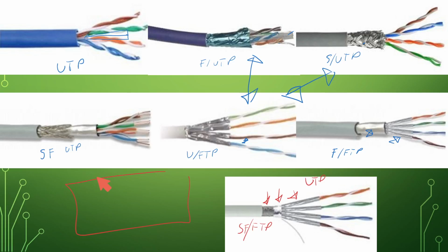Now, things have also gotten better with VFDs, variable frequency drives. It used to be that to turn a motor on, a contactor closed and it was full power to the motor, like flooring your car and spinning those wheels. That caused a huge EMI coming off of it. Now with VFDs, we can do a ramp up. You can slowly spin the motor up, so you're not just full powering it. You're kind of feathering the gas in. So it's a much slower process, but it's not creating as much interference.